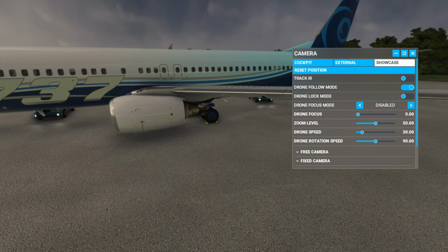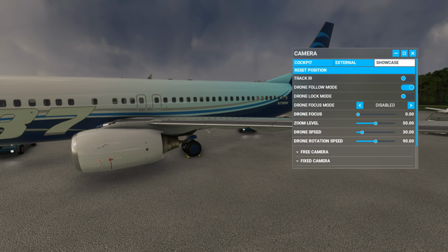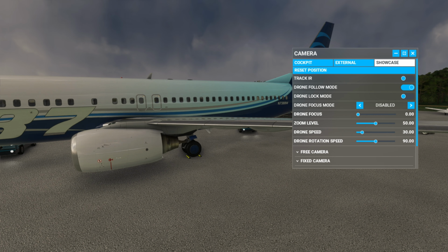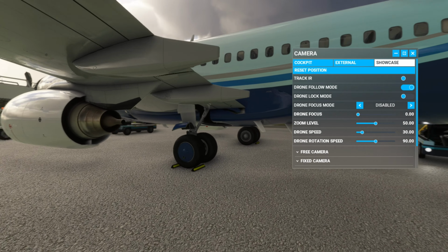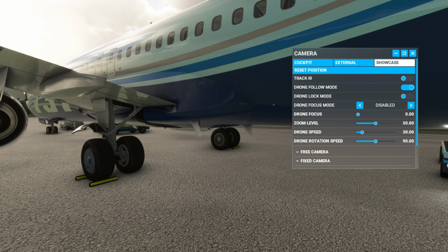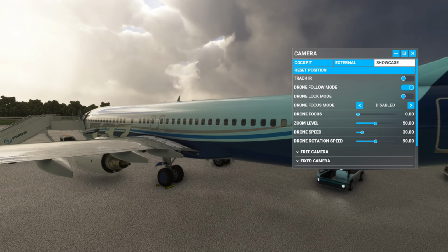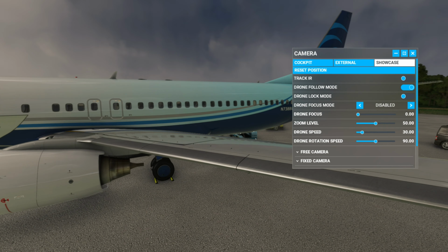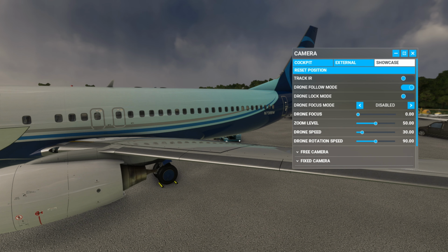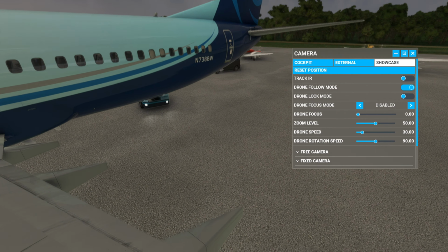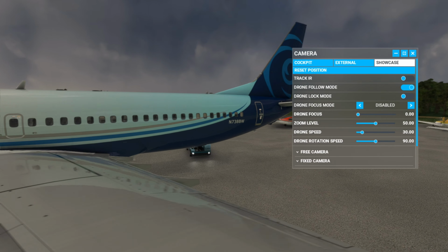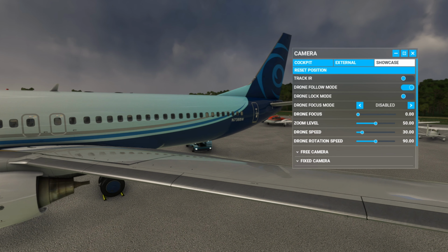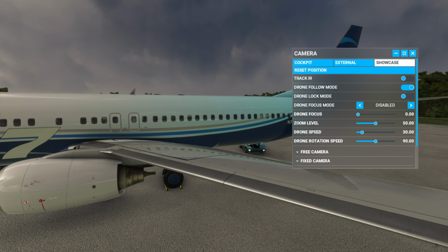The spoilers come out either in flight, in the in-flight detent, in order to bleed off speed in flight, or when the airplane touches down with the main landing gear. Those are the two wheels that are just aft the center line on the longitudinal axis of the fuselage. The main gear come down first. They have what are called weight on wheel switches, which will tell the airplane's onboard control systems that we have weight on the wheels. The airplane has touched down on the ground, and they will deploy the ground spoilers, which are the outboard most panel here, allowing the spoilers to come up and spoil lift on the wings. This keeps the airplane from bouncing after initial touchdown and enables the airplane to lose speed after touchdown.